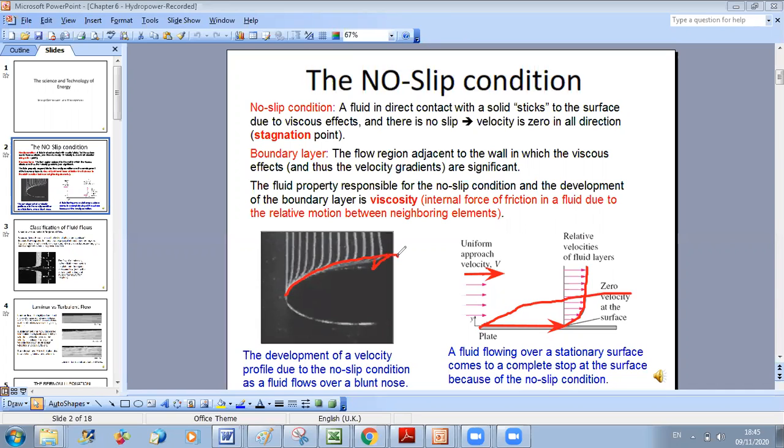Now, why are we talking about boundary layer? Why do I want to introduce you to boundary layer? Because we will see mainly that our applications are far from boundary layer. So in our applications, we will neglect viscous effects. Viscous effects are effects that lead to smooth variation of velocity, so here you vary from 0 towards final velocity. But if I am working far from the wall, I can say that my velocity is uniform, no change in velocity.